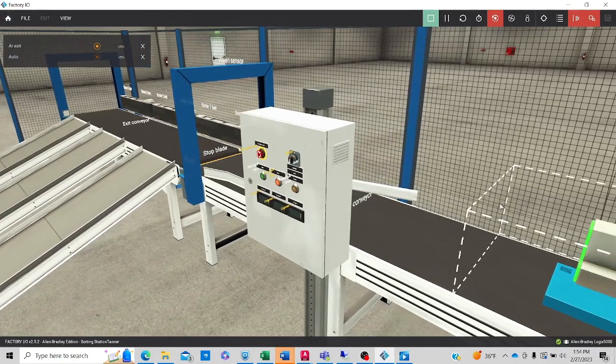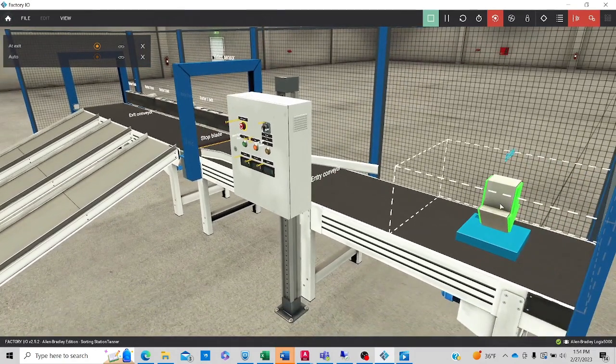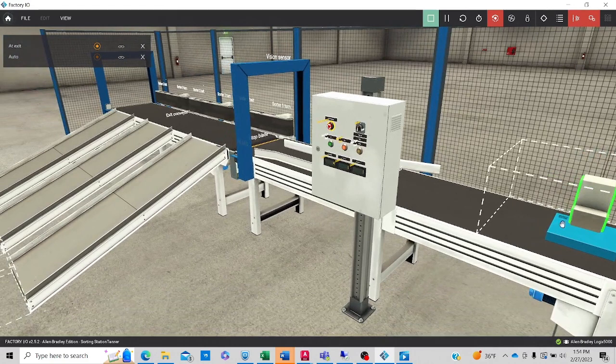As you see here, there's parts. It'll send parts down this conveyor, read that QR code with this vision sensor, sending the part to the correct slot. Right now I have these blue unfinished parts going down the first chute, green unfinished goes down the second, and the finished parts go down the third. Based on that QR code, it will open this arm and turn the conveyor on, or open this arm and turn the conveyor on.